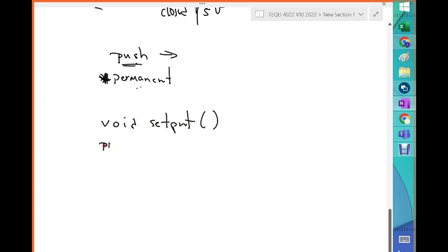So we set pin mode 2 as an input. And then let's make a comment. Pin mode is an input for what? For what switch? Switch number 1. And switch number 1 is for what? The low level or the high level? Low level.